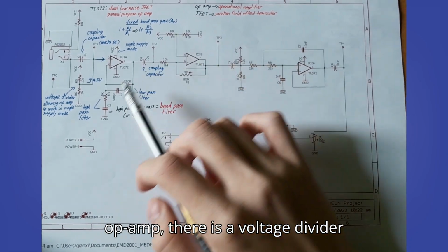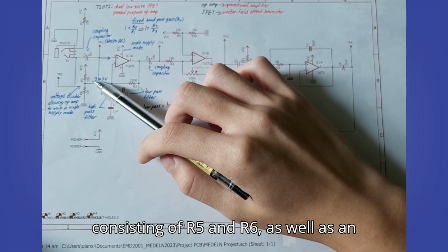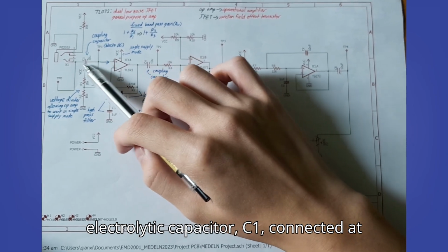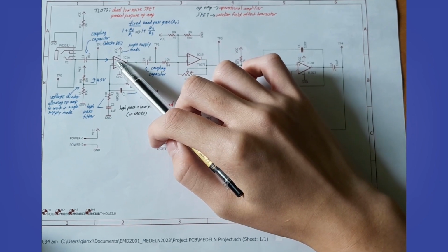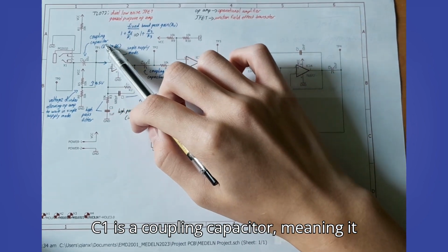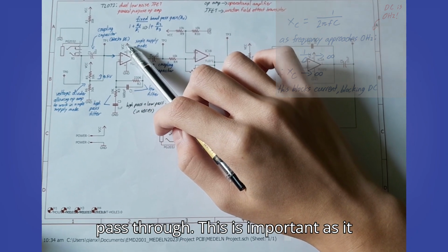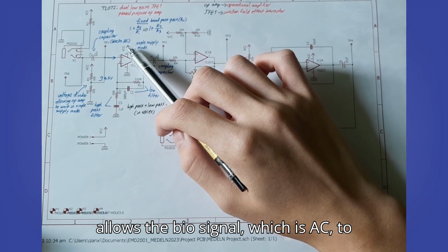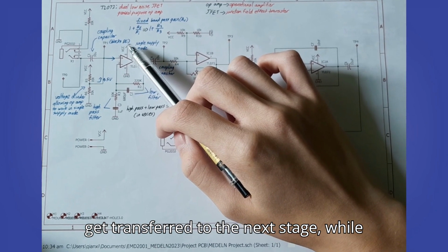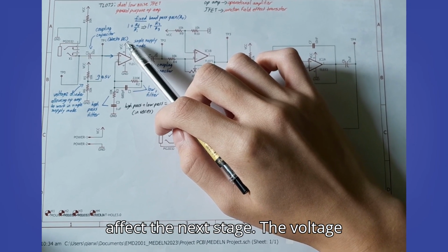Before the op-amp, there is a voltage divider consisting of R5 and R6, as well as an electrolytic capacitor C1 connected at the non-inverting input of the op-amp. C1 is a coupling capacitor, meaning it blocks DC voltage while allowing AC to pass through. This is important as it allows the biosignal, which is AC, to get transferred to the next stage, while any DC bias or offset value will not affect the next stage.